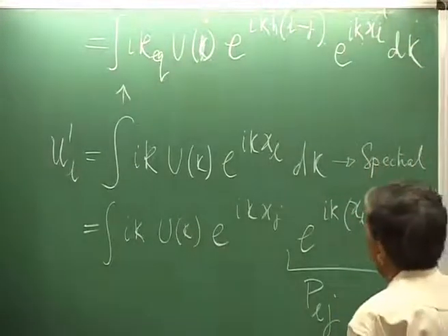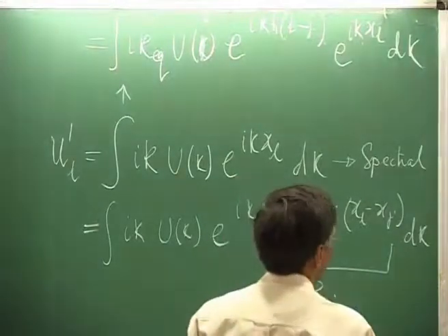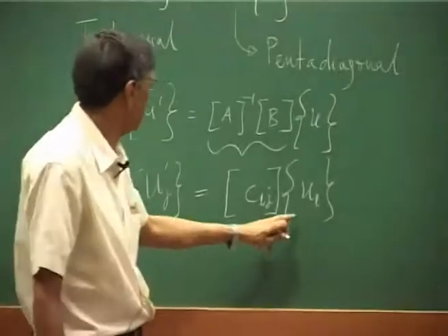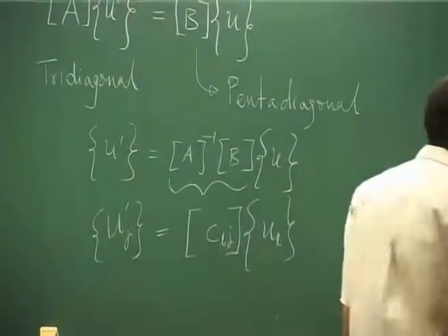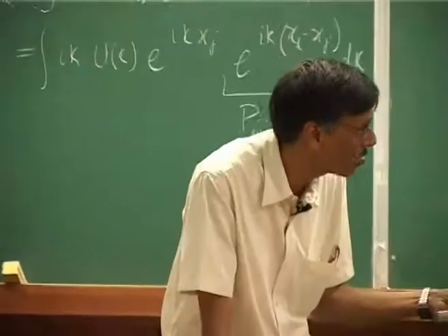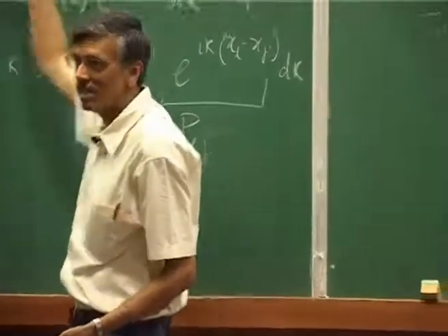This is what we want, right. So what happens is, if I look at this, every uj or ul has been projected to the jth point, and that projection operation is given here, right. This is the projection, and then of course you brought the phase back to the jth node, that is what we are looking at. So the quantity within that brace is nothing but ik equivalent, right. That is your ik equivalent.